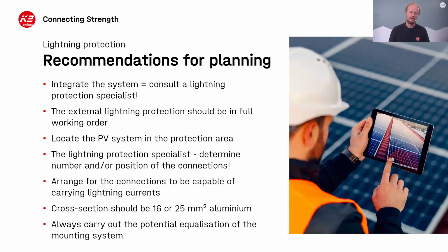One of the points for the PV is that we can always ensure that there is equipotential bonding between the components, right? So we've jumped a little bit from equipotential bonding to lightning protection, and here we're saying when the lightning protection is there and integrated with the system, you always want to ensure that bonding is there, regardless of any other comments on frame insulation or personal protection or anything like that.